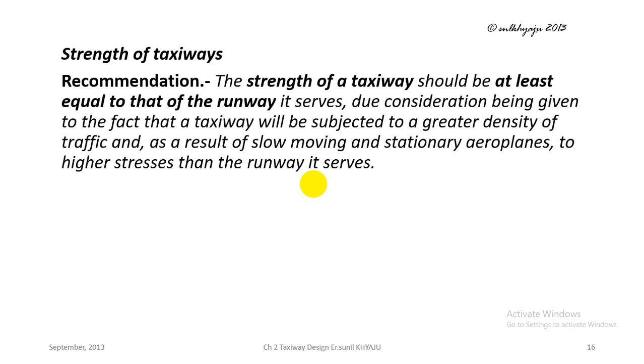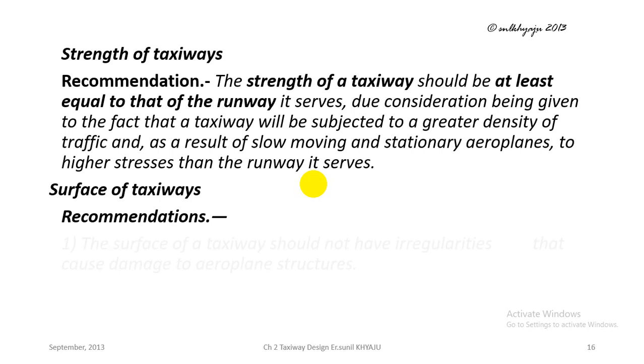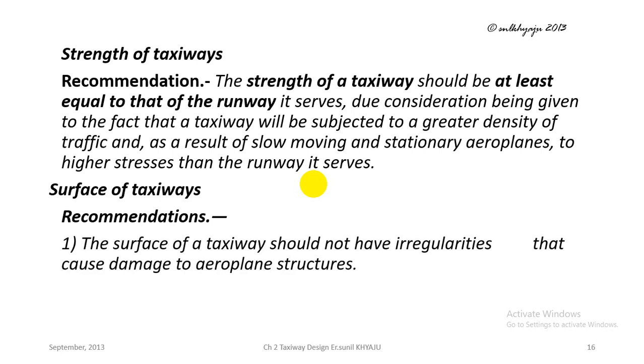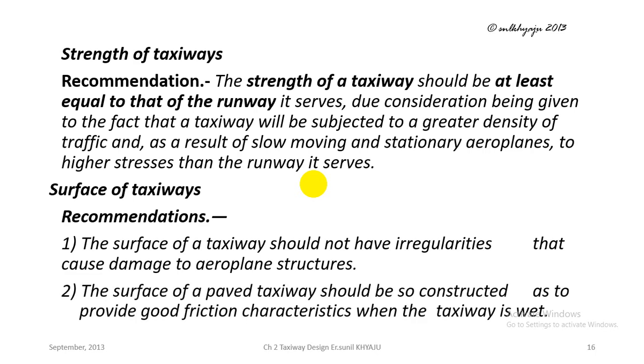Strength of taxiway recommendation. The strength of a taxiway should be at least equal to that of the runway. Surface of taxiway recommendations. The surface of a taxiway should not have irregularities that cause damage to the aircraft structure. The surface of a paved taxiway should be so constructed as to provide good friction characteristics when the taxiway is wet.